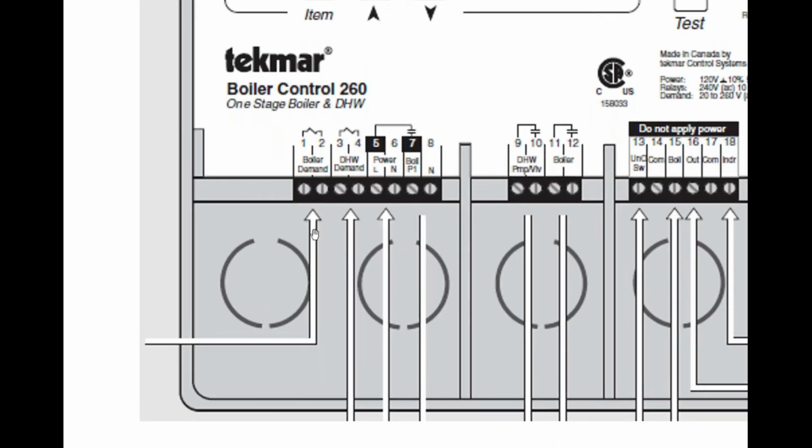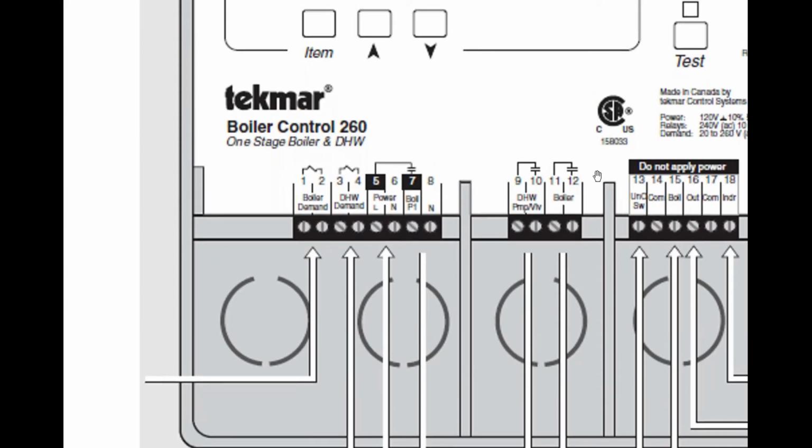And what do you see right there? That is the symbol for a relay coil. So if I put my thermostat or end switch from a zone valve or just a jumper across the 1 and 2 terminal, I'm going to energize that relay coil. What's going to happen? Well, this boiler normally open switch on terminals 11 and 12, that's going to close.